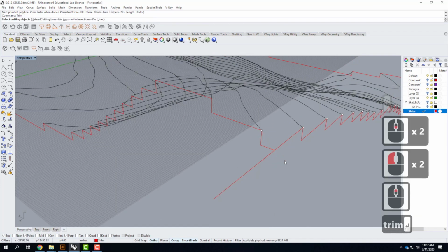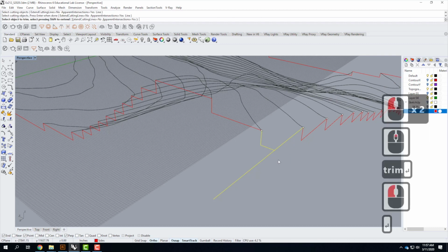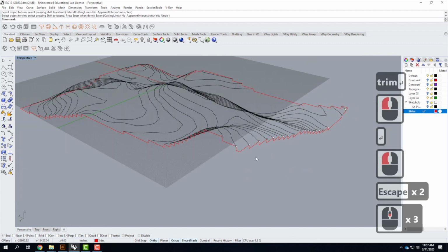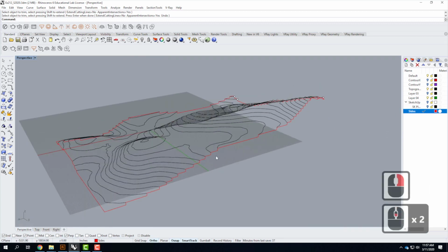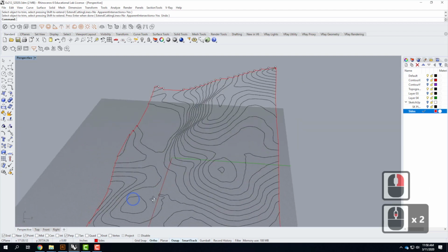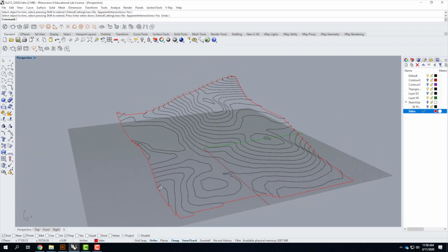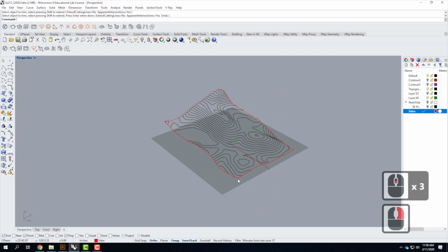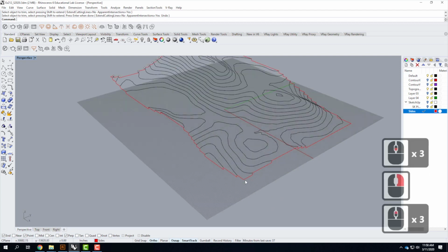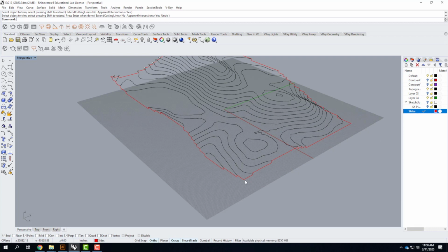So we'll go ahead and trim like that. And now we have that corner resolved. We work our way, there's the top, it's level. We work our way back down this side, all of that looks good, and we're back to where I started. So I've now worked through all of my corners, and that's going to vary depending on your particular terrain as to how those corners come together. In very rare instances, a contour will be exactly at one of the corners. That's okay, but it's not always going to happen.